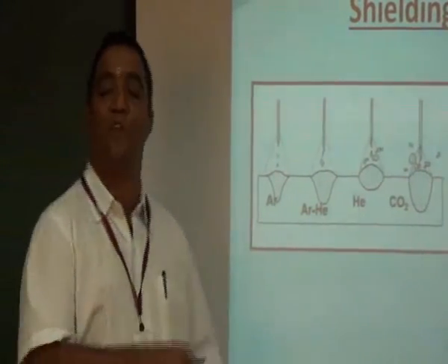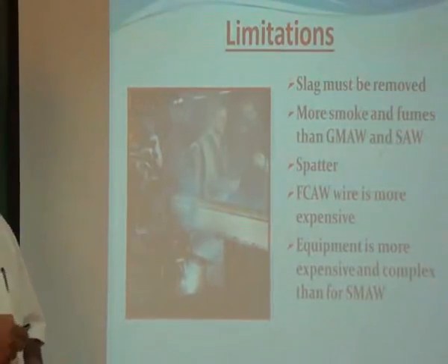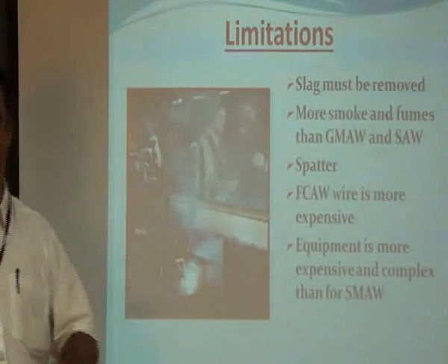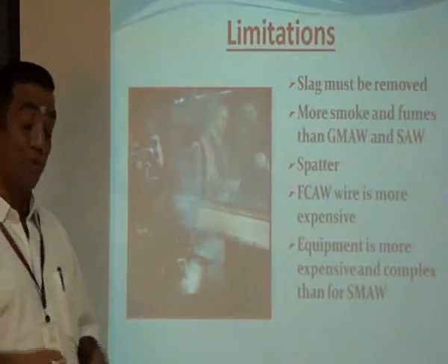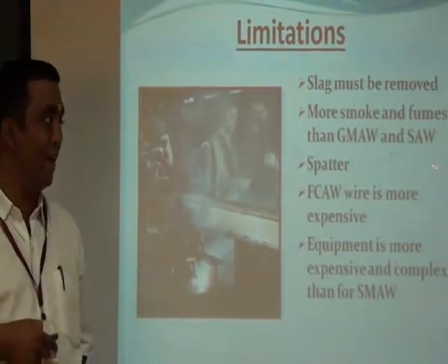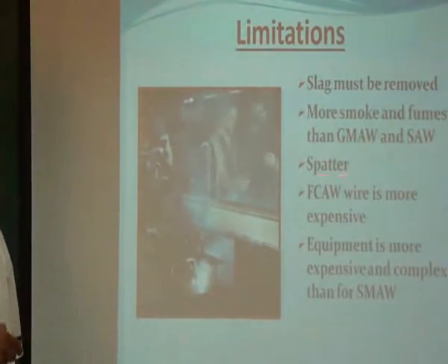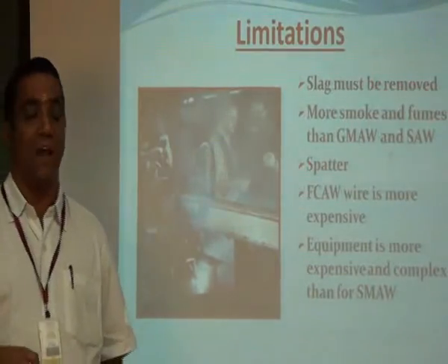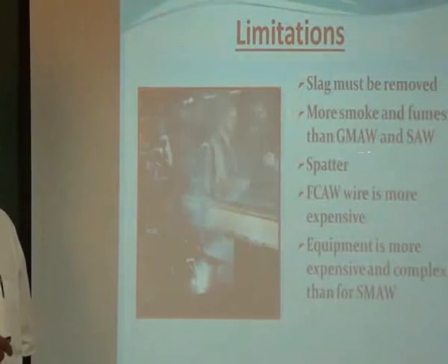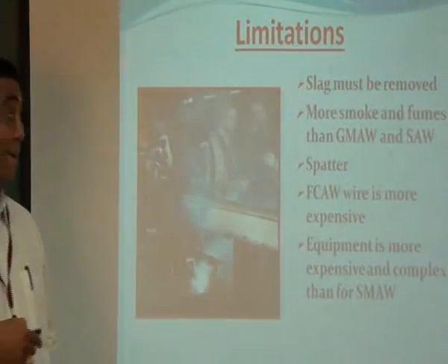Remember, these flux cored wires are in use in industry. The welder will find it very, very difficult, because he has to inhale contaminated air, though he will be wearing protective clothing. He has to inhale the gas that is coming due to the flux, and also due to this particular shielding gas. And this is one of the reasons for more smoke and fumes. That's why the welder does not prefer this welding process. But it has a lot of applications.